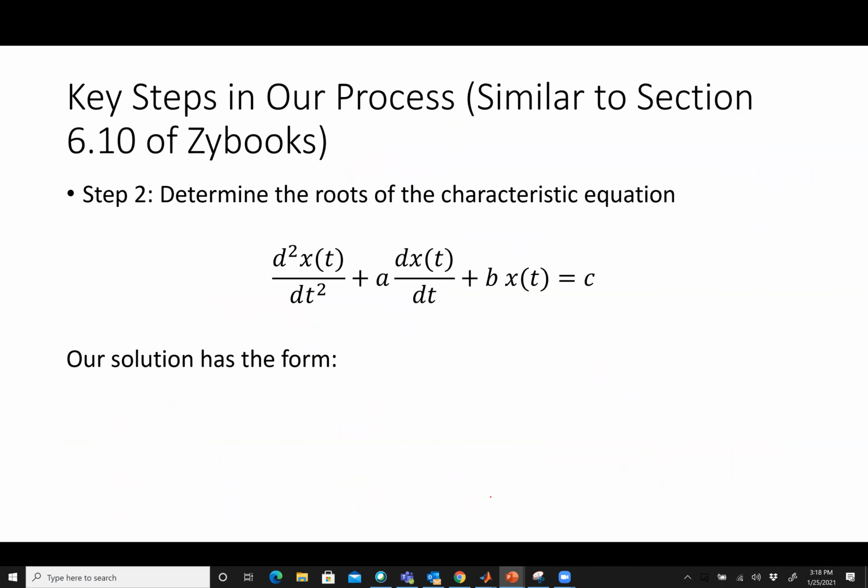All right. So if I have that as my differential equation, remember my x of t in this case is Vc, but it could always be IL or VC. Basically, the things that store energy, the inductor current and the capacitor voltage, are the things we write differential equations for. I'm never going to ask you for a differential equation for the inductor voltage or the capacitor current. We only write the differential equations for the energy storage variables. And you will always be explicitly asked, give it for Vc or IL. That's not something you'll have to guess on, okay?